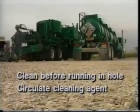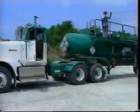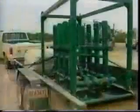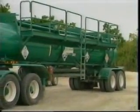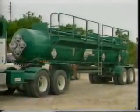If the engineer suspects that dirty tubing is in the hole, then acid or another equally effective cleaning agent should be circulated. The major components required for this matrix acid treatment are an acid transport, a pump truck, and a high-pressure filter unit. The acid transport has 3 independent storage compartments. Contents and volumes are clearly identified.